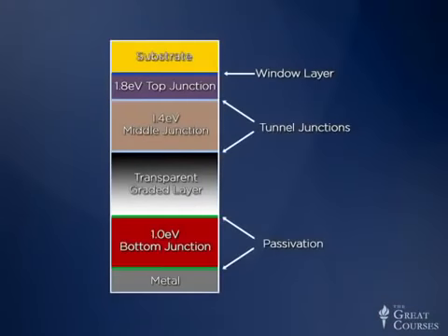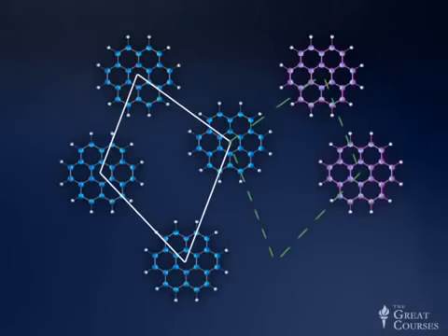Well, traditionally, semiconductor processing and growth have worked based on the process known as epitaxy, which we described in the solar lecture, where we were talking about triple junction devices, about growing perfectly lattice-matched crystals on top of one another. But now, this panoply of materials I just described don't even necessarily all have lattices. Some of them could be amorphous, some of them could be crystalline, some of them are of shapes that are even non-planar. And so it's not obvious at all how to use our traditional stacking of crystals on top of each other to build stacked heterostructures or heteromaterials.